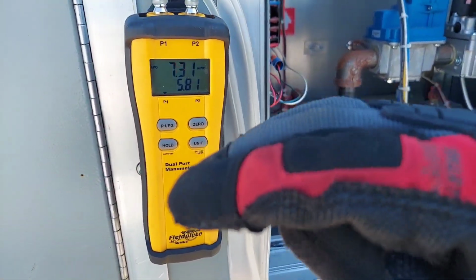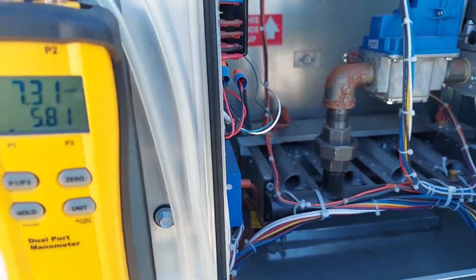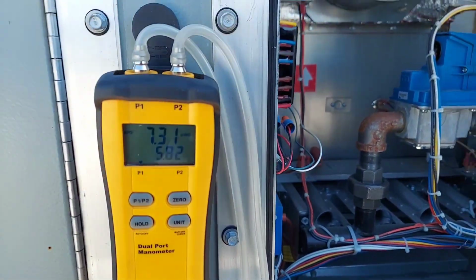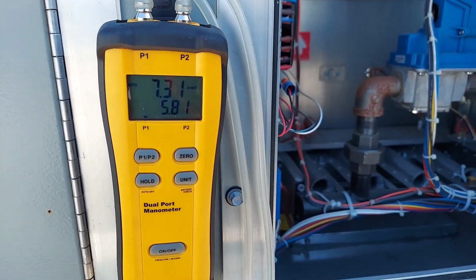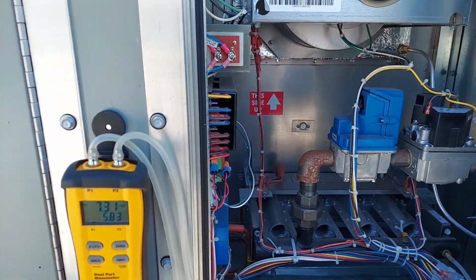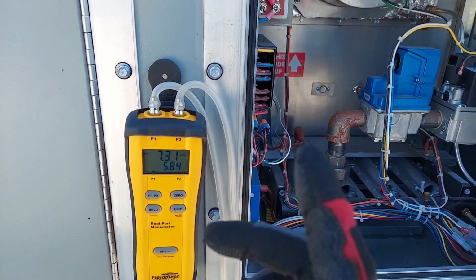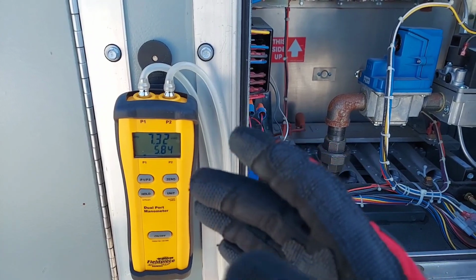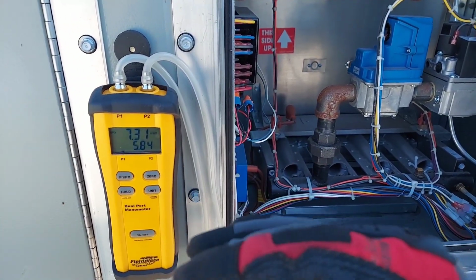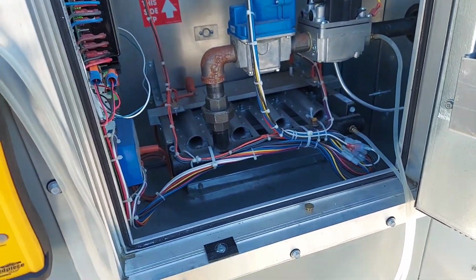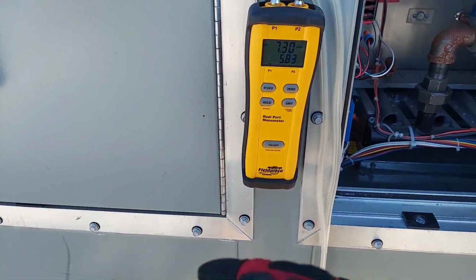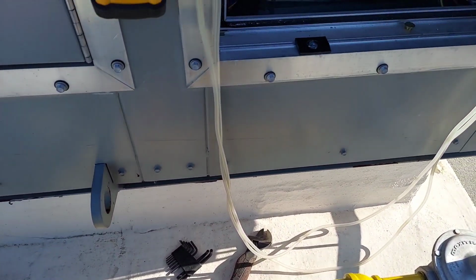You want to find out what the maximum is and stay closer to the maximum set point, just to give some flexibility. You're better off staying closer to the maximum set point, simply because on a cold day when there's high demand, the gas pressure will drop. Usually that's what happens.